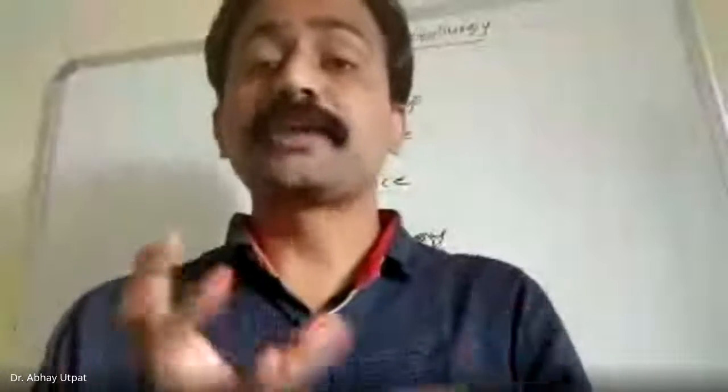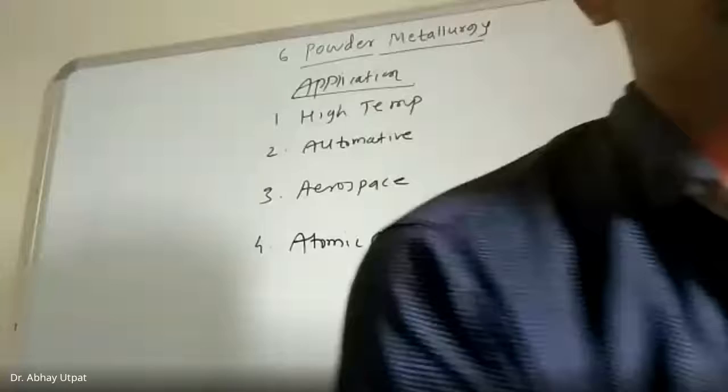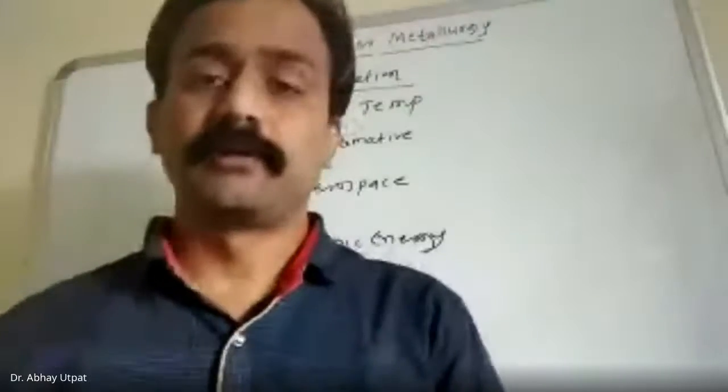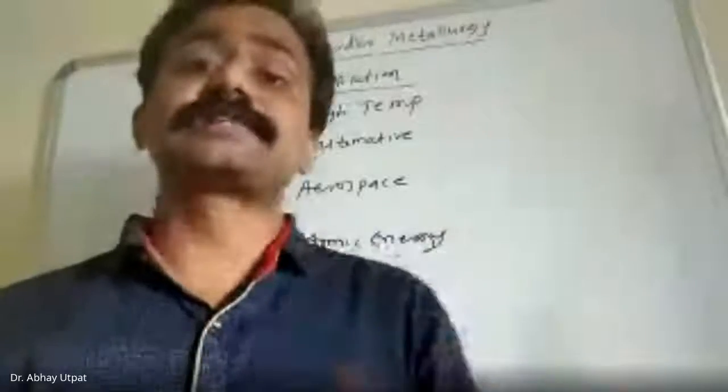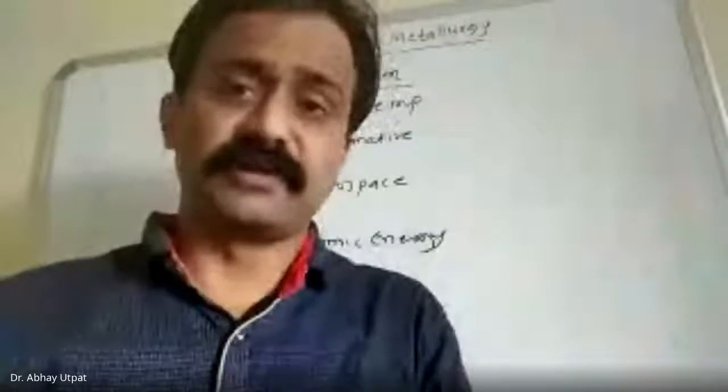For withstanding the higher temperature, the capacity of the metal should also be more. And how can you give shape to the components? Casting of this component is very difficult, pouring metal at about 2500 degrees Celsius. So producing these shapes by casting method is difficult.